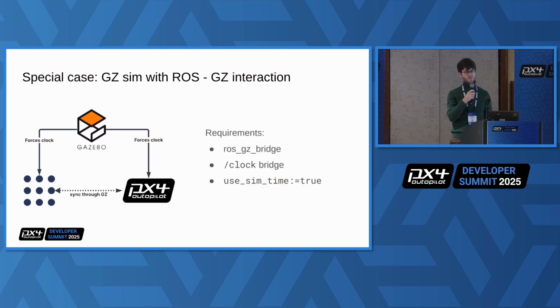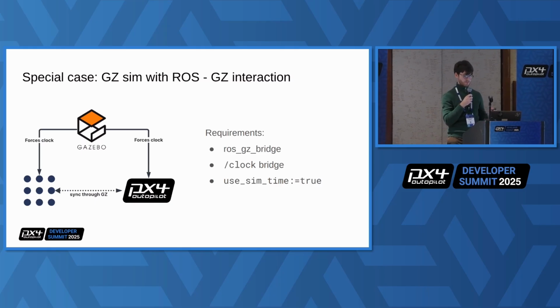Actually, it can be, I won't say harmful, but could have unexpected results, because the agent is ROS2 agnostic. It cannot synchronize the client with the Gazebo or ROS clock. It synchronizes it with the system clock. So as long as your simulation is running with a real-time factor equal to 1, you're good. But the moment it starts running slower or faster, you will keep having warnings about timestamp synchronization being out of sync and trying to resynchronize, because maybe your simulation is running at half real-time factor and it doesn't add up anymore. So consider switching it off in this scenario.